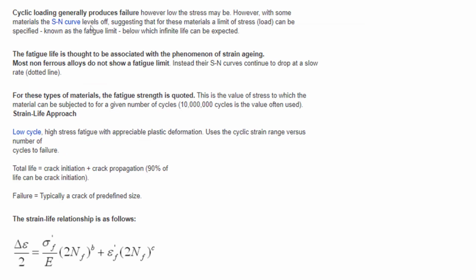Here there is some description about the stress-strain curves. You need to remember, if you're going to deal with fatigue analysis, we need to know about the stress versus number of cycles curves. That is mandatory. And with respect to that, some rules come into account, that is, criteria: Goodman, Gerber, Soderberg, Brown Miller, and there are different criteria.